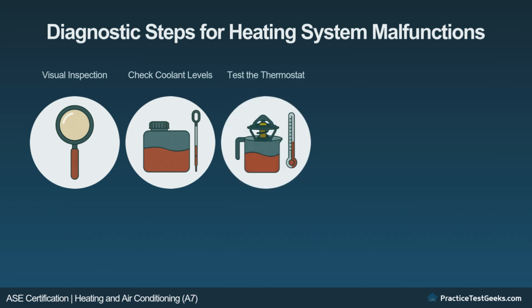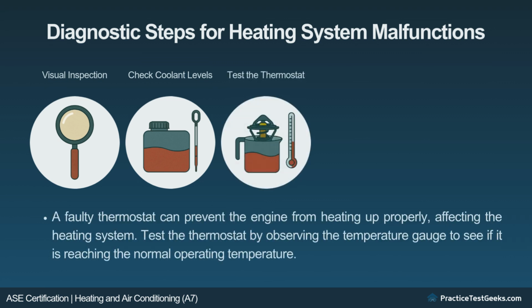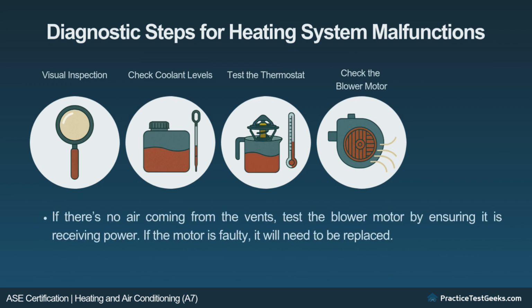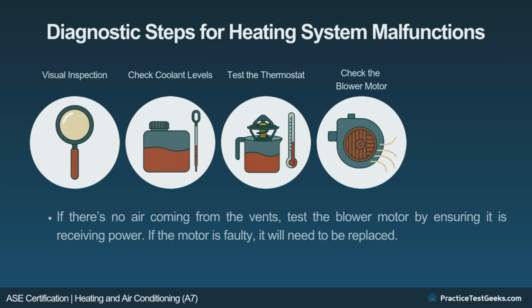Test the thermostat. A faulty thermostat can prevent the engine from heating up properly, affecting the heating system. Test the thermostat by observing the temperature gauge to see if it is reaching the normal operating temperature. Check the blower motor. If there's no air coming from the vents, test the blower motor by ensuring it is receiving power. If the motor is faulty, it will need to be replaced.